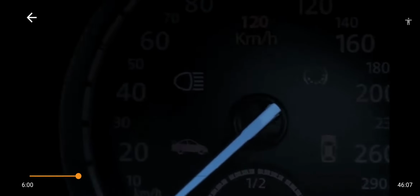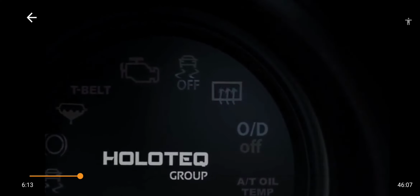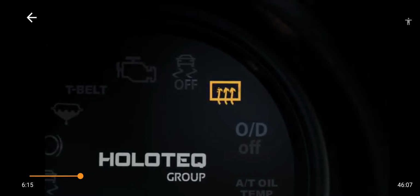High beam light indicator. It should be turned off when facing vehicles. Fog remover from the rear window indicator. It should not be used except in the existence of fog on the rear window. Seatbelt use reminder indicator. Passengers of the front seat at least should use the seat belt. Trunk open indicator. The trunk must be closed before turning the engine on.